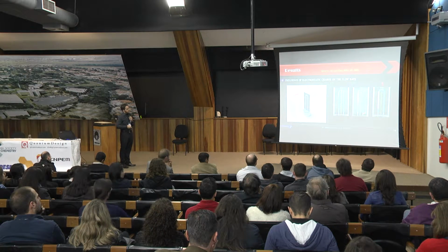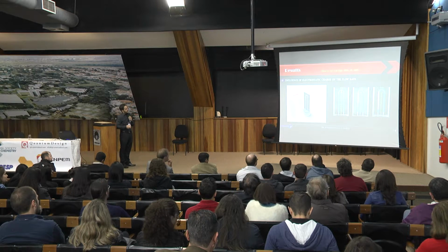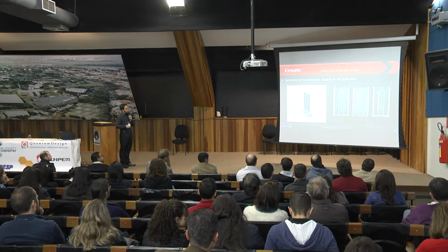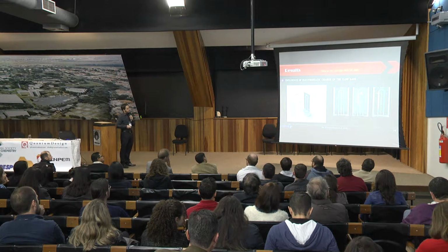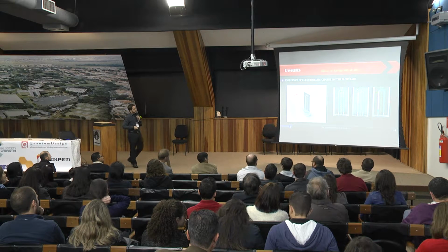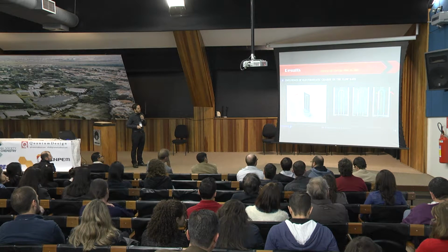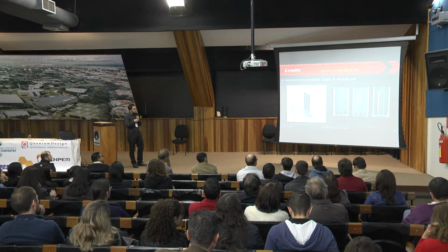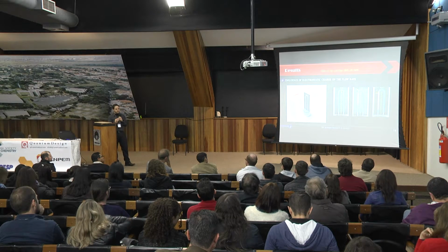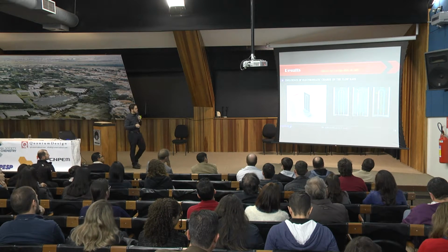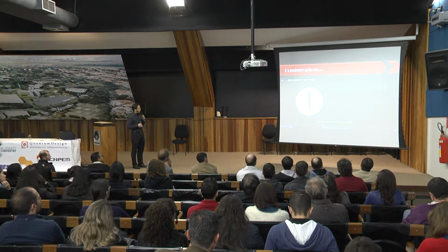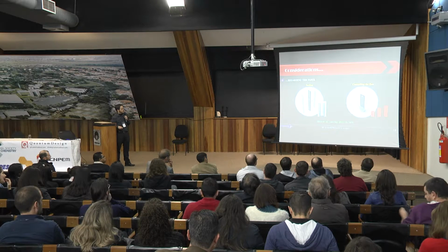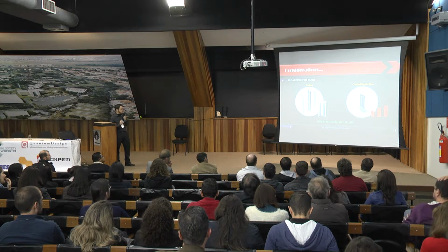And here a bigger hole, so we can shift the meeting point of the liquids to the left because of the presence of charge in that part. When we increase the area that is in contact with the charged surface, we can shift even more. So we can control the flow rate in one of the channels by increasing the area that is in contact with the charge.